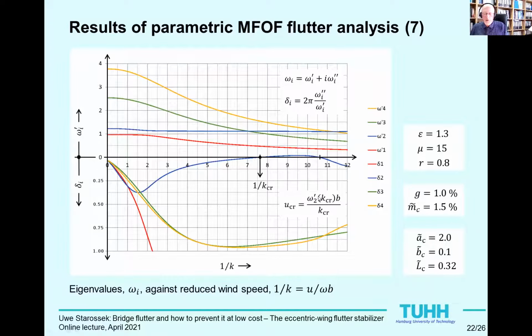When the wing length is further increased, the boundaries of the critical range, the range where delta 2 is negative, move towards each other, then merge into a point which finally disappears when this branch completely withdraws below the zero line. The merged point condition marks the wing length above which no flutter occurs. Given the glancing intersection between the delta 2 branch and the zero line, a small additional increase in wing length is sufficient to reach this merged point and no flutter condition.